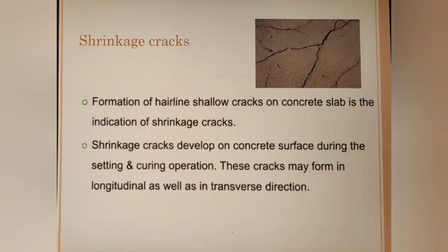Second type of failure is the shrinkage crack. So in the figure you can see the hairline cracks developed, which is mainly due to the setting and curing operation. So this type of crack develops both in the longitudinal and transverse direction.